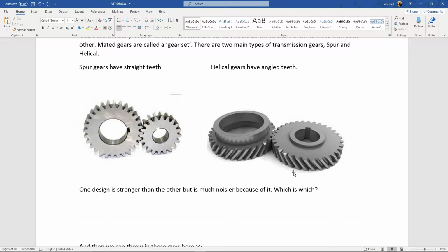And hopefully you will all get to this point somewhere in your life, because I know we all want to build race cars where you get to come back and remember this. But a big upgrade is swapping from these helical cut gears, which came from the factory because they're quiet and reliable, to spur cut gears, which are way stronger. At the trade off of the car might be a little bit noisier, but what do you care? It's a race car. We can't even hear it over the exhaust anyway.